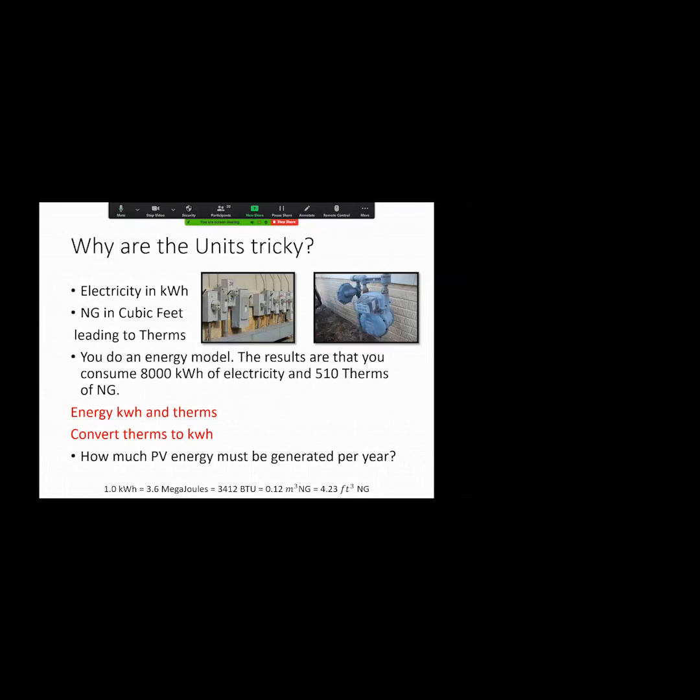So, let's see where I'm at. Electricity is tracked using kilowatt hours. This is total energy consumption. You might also have a peak demand charge, which is peak power flow for a 15-minute period, which will be kilowatts. These charges can be pretty substantial. So if you're a big commercial facility and you have really big equipment that's going to be running, the power company has to be able to meet your demand.